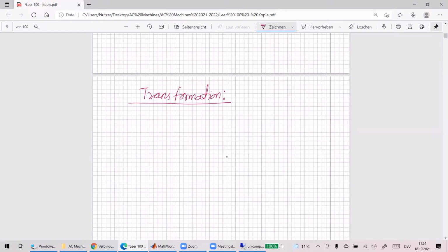But people are not trying to do that now. That was the previous approach. Long back, people used resonant controllers, which can control a particular frequency. Let's say you want to control the fundamental frequency, which is 50 hertz. You want to control the 50 hertz component perfectly.